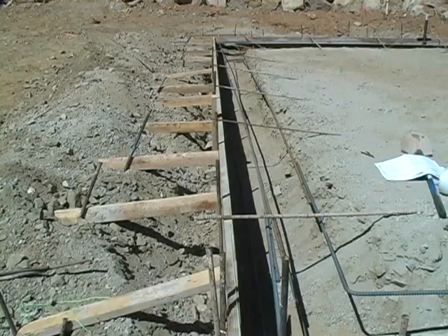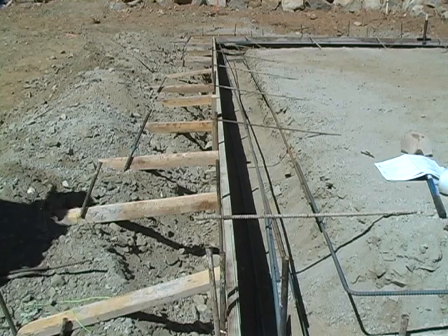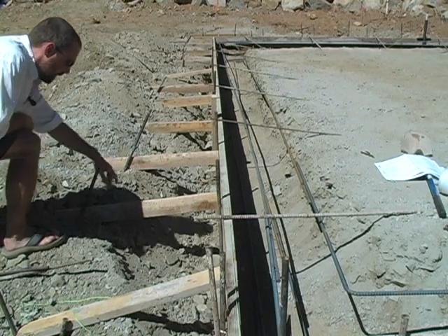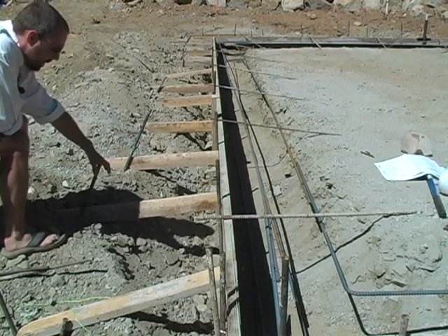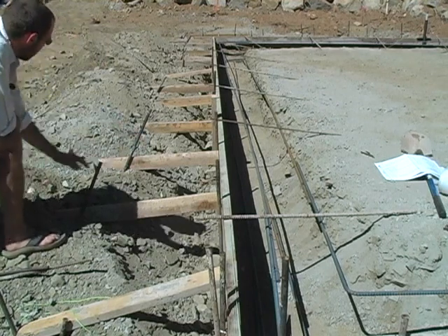On a larger foundation where you have more mass of concrete behind the walls, you want to make sure to really brace it off well. You can see here we've got not just angle braces, but actual solid braces coming out to stakes that are back down into the ground here. These are really holding these firm and then nailed on to the form boards there, as well as the vertical stakes as well to hold it in place.